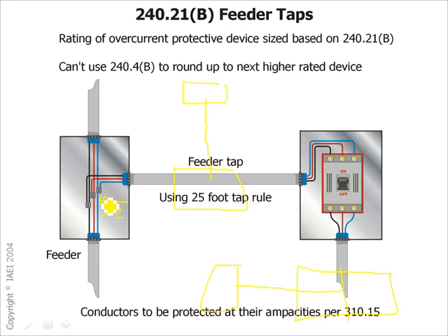Does that make sense? You tap inside the enclosure, and because it ends in a fuse, it protects the circuit. Yeah, you can tap it and land it on a fuse, and that protects the control circuit. Or there's also an exception where you don't even have to put a fuse. Remember when we talked about there's a few exceptions where you don't even need a fuse.